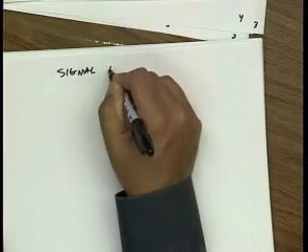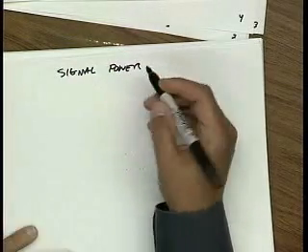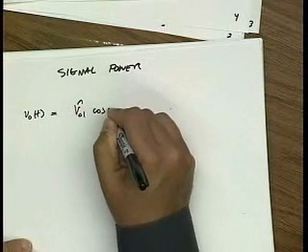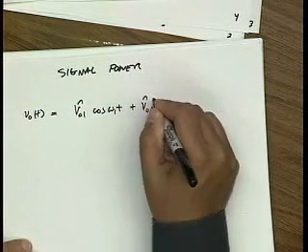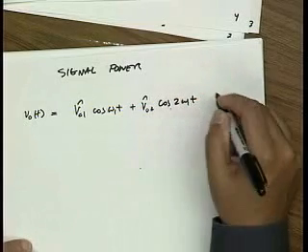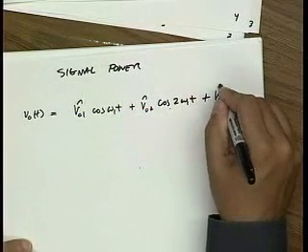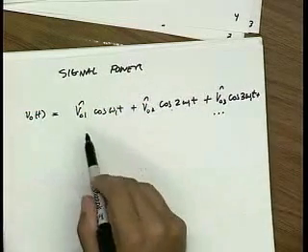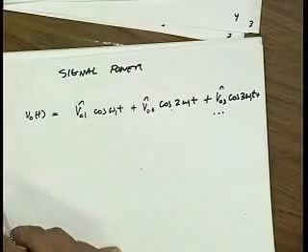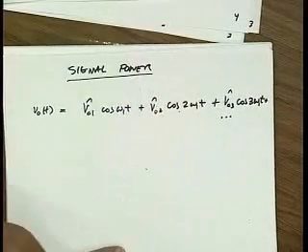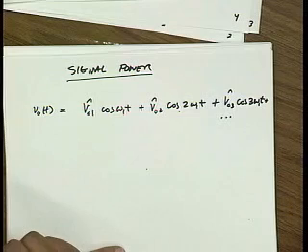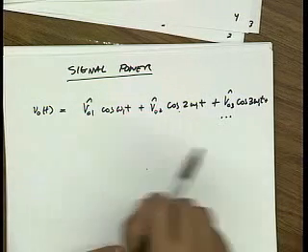So let's start out with the signal power. Our output signal is basically a Fourier series. We put in a sinusoidal input, and output we have basically some signal at the same frequency plus all the harmonics. Now remember, a linear time invariant system cannot generate output frequencies that are not in the input frequency. So you need a nonlinear system to make this happen.